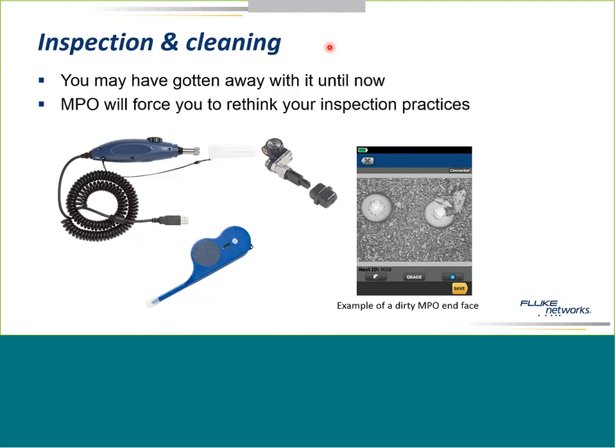That dust cap, there's a reason it's called a dust cap. That's where the dust is stored. Maybe they could be called a port protector. But anyways, you really want to inspect your connectors before you plug them in, because if you connect a dirty connector, it's going to transfer that contamination.